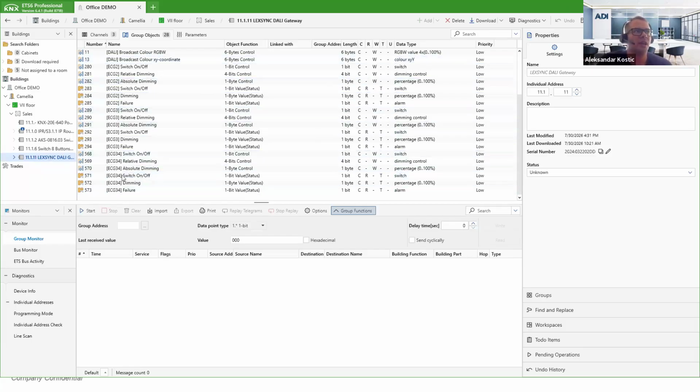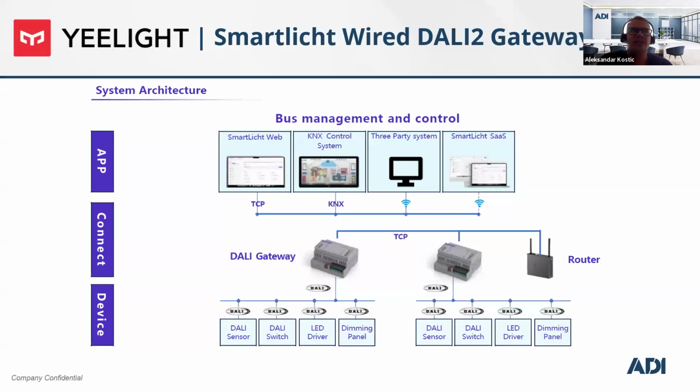So when you do this and when you configure those devices from the ETS, then on the web interface of the DALI gateway, you can discover those devices like they are part of the DALI bus. And as soon as the DALI gateway sees those devices as part of the bus, the same way how the DALI devices are imported in Control4, also those KNX devices which are mapped are imported in Control4 as well.